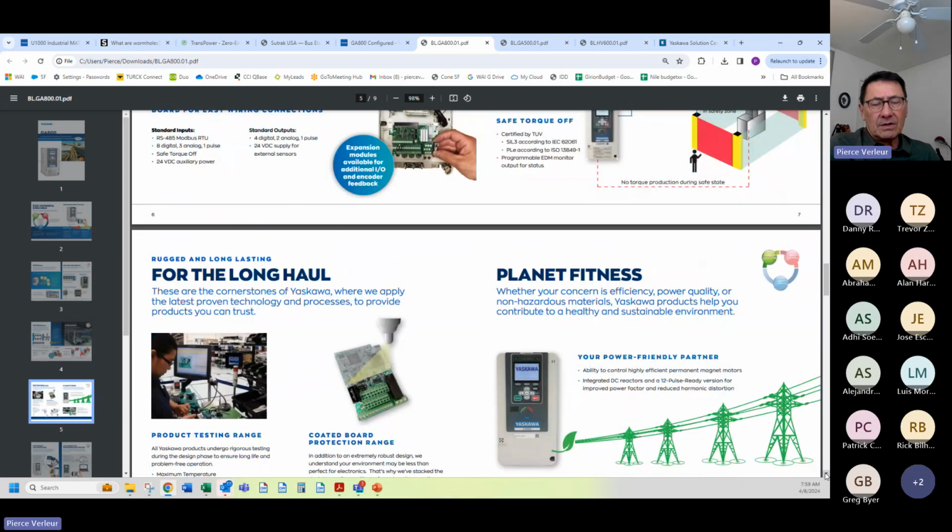By the way, all of our industrial protocols except Modbus RTU, which is an RS-485 protocol, are option cards. Why? So that we can make the drive the same way all the time. So the native serial COM is Modbus RTU. If you want Ethernet, you got to put a card on our drive.